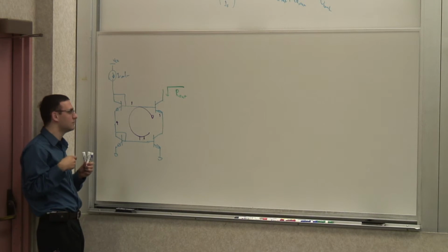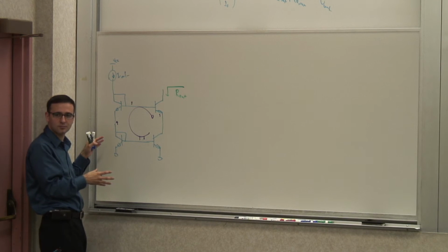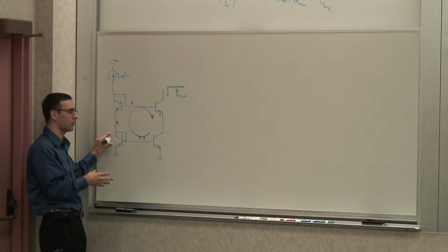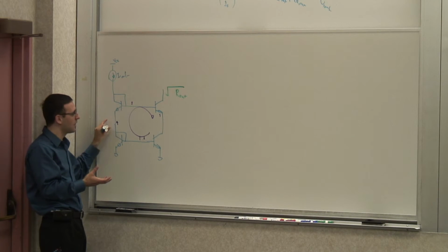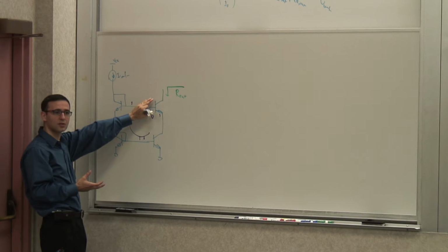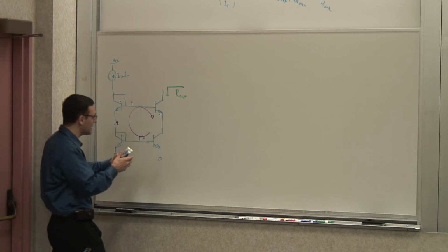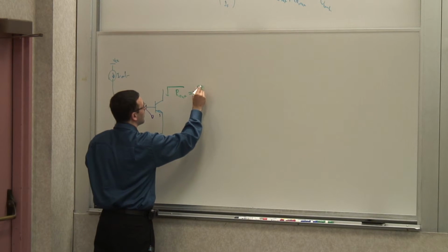And if you write down this, you actually draw the small signal model for this. These are simple. These are just 1 over gm and 1 over gm. I'm saying 1 over gm, alpha over gm, alpha over gm. Diode connected transistors are easy. And draw the actual small signal model for this, and apply test voltage and measure the test current. You will see that because of the second signal path, this turns out to be beta RO over 2.